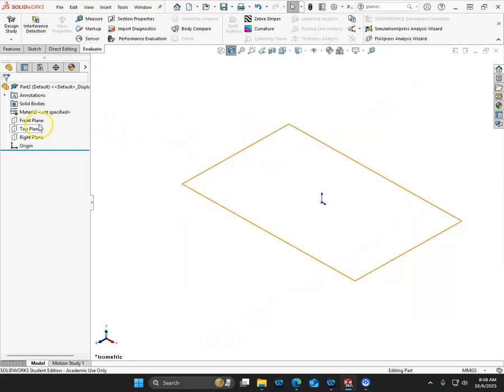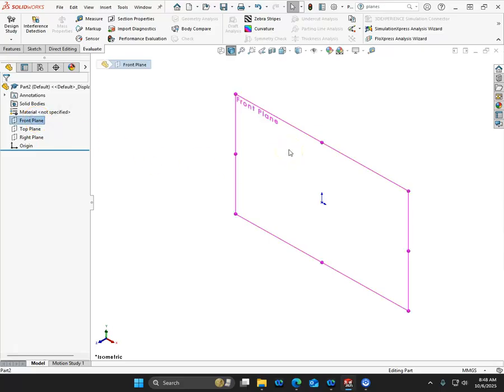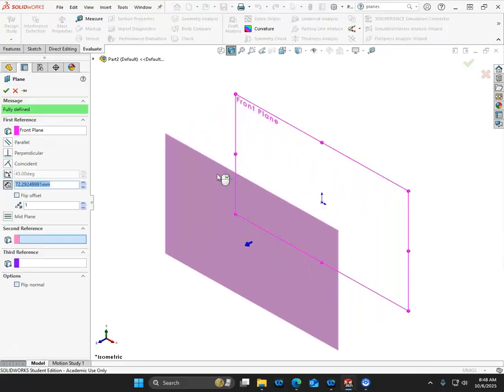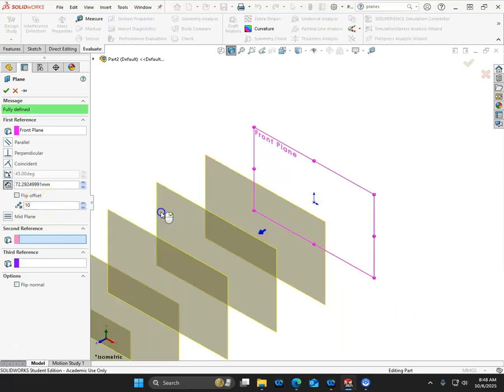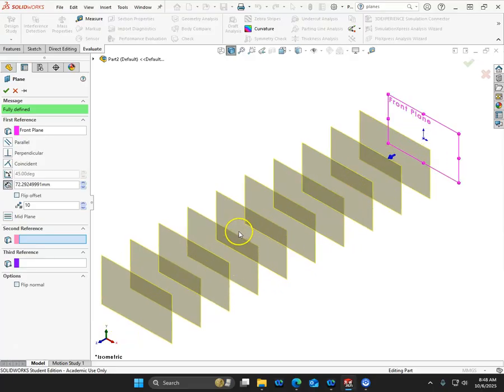All right, the easiest way to create an offset plane is pick the plane that you are going to offset. You'll get a move symbol, left click, hold down, and drag. And that will put you front plane, a distance off of, and if you want it to go the other way, flip the offset. If you want 10 of them, you can, let's see, is it tab? There they go. I had to click out in the work area. But I can set up 10 and they will each have the spacing that I give them. But when they're generated, I'll be able to define each one individually.